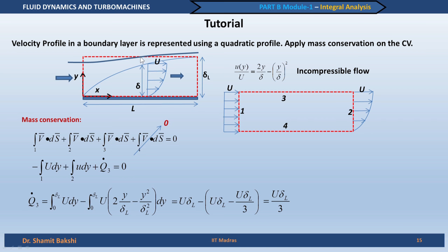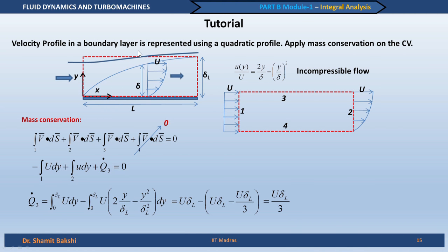Because by the definition of the streamline, we know that if we draw a tangent to the streamline, it should show the direction of velocity. Now, the fact that on this control surface you have a v component of velocity means that the streamline should bend; it cannot be parallel to the plate. So, from this simple application of mass conservation we can see that in the free stream, outside the boundary layer, the streamlines will slightly bend to account for the small velocity present